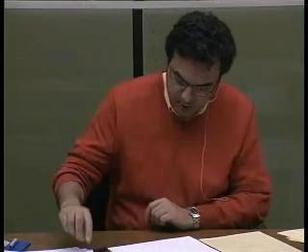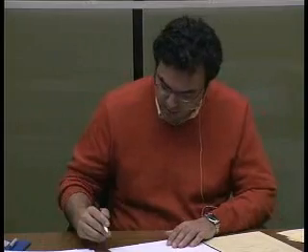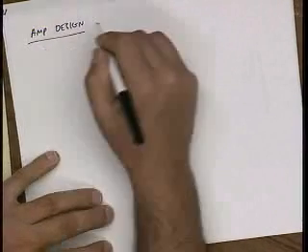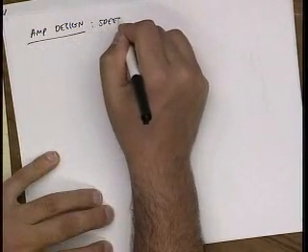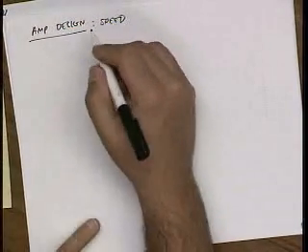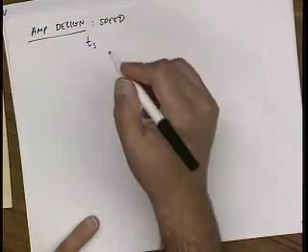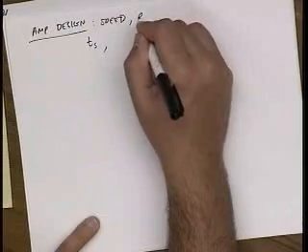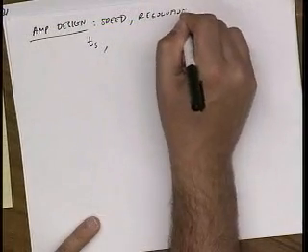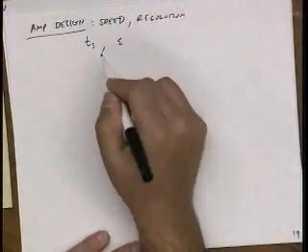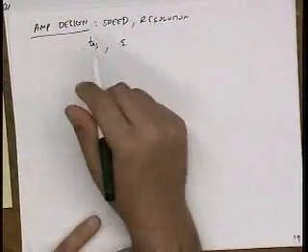I just want to talk a little bit more about amplifier design. So usually when we're designing an amplifier, we have a couple of important overriding considerations. One is the speed, right, which is really the settling time, and the other one is resolution, which is epsilon. So we want to settle within a certain time, within a certain accuracy.